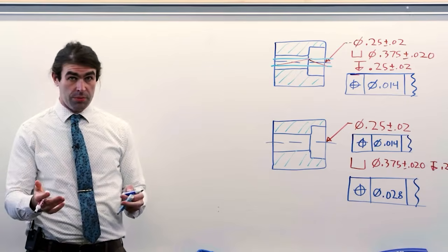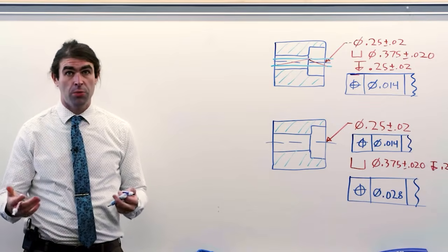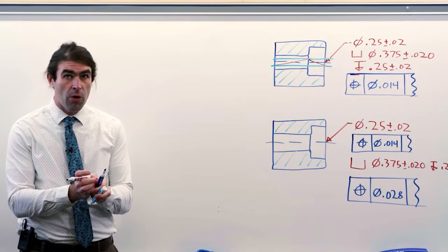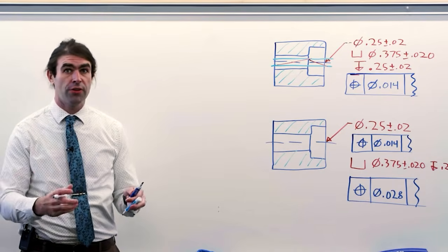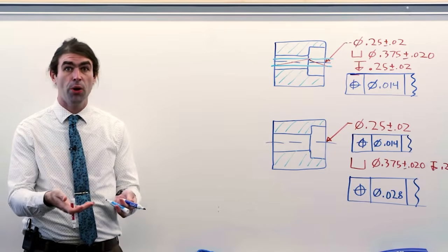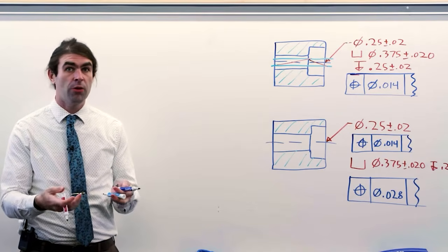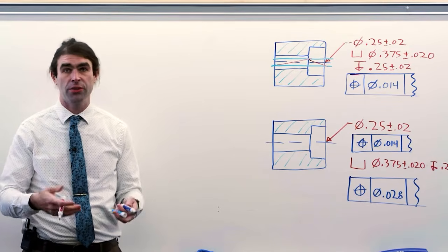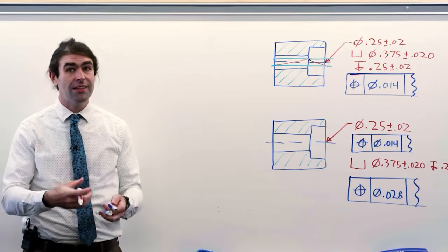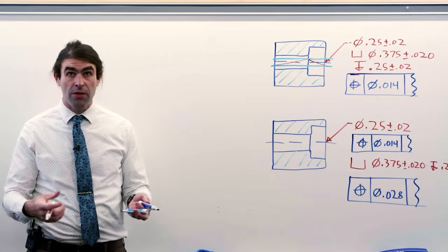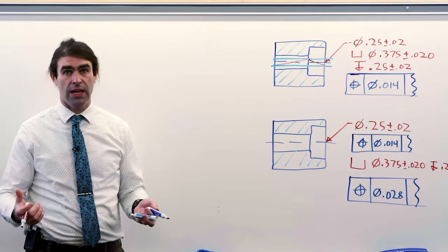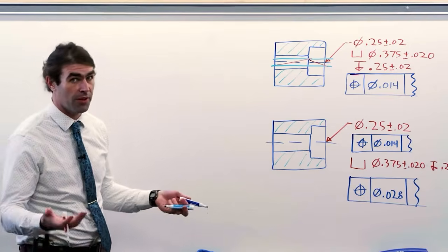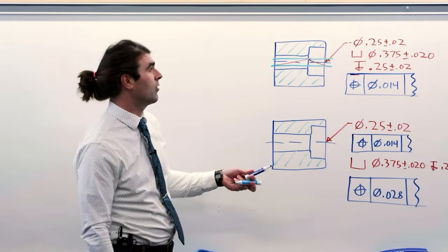Now, this can be fine, but it typically is more expensive. Typically you want a kind of small hole because you need bearing surface for the underside of a bolt head, but often the counterbore could get larger. That wouldn't affect the design, unless it's running up into a thin wall condition or something. But typically the counterbore can grow more than the hole can, right? If the hole gets way too big, you're not going to have any room for bearing surface for the bottom of the socket head cap screw or whatever you're using.